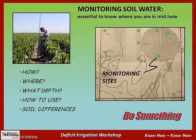Monitoring soil moisture is something that we think is becoming very feasible. We've got some systems where we put watermark systems in, and we've buried the line underground about 400 feet to get out to a data logger that you can push a button and you see 35 days of record of your moisture at 6 different places in the field. That costs us about $800 a field to do that. The cost to send that pivot around is probably anywhere from $1,500 to $2,500 just to send it around one time. So you can pay for all of that in less than a full revolution of a pivot.